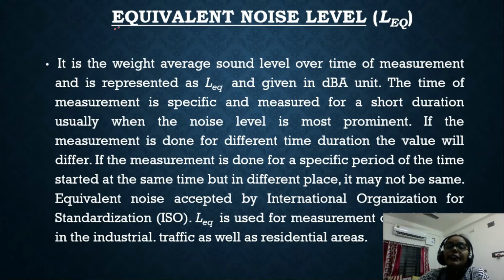Next one is equivalent noise level. Now, as I told you, when we are facing road traffic noise, there are so many vehicles, so many sounds that we are exposed to. Here we are taking the weighted average of the sound level over a specific time span, and that is represented as L equivalent, given in dBA unit.